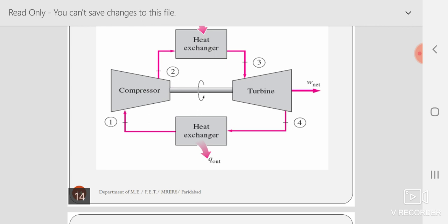So, as a first preference, you will omit the reciprocating compressor. Automatically you come to centrifugal or screw compressor. Now you have to see the advantages of centrifugal and screw compressor. In a centrifugal compressor, the vanes rotate and compression happens. In screw compressors, there are two screws. There are threads in the screws, and between the threads the gases enter and get compressed. Now you have to see the advantages and disadvantages of both.